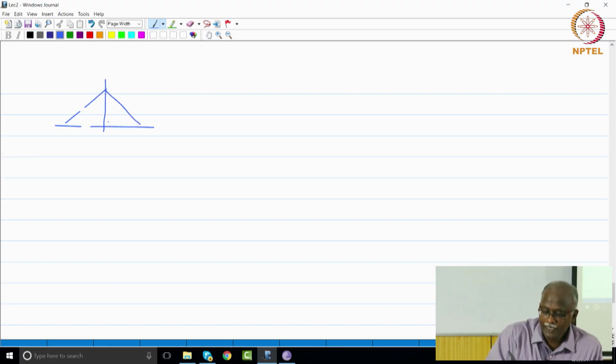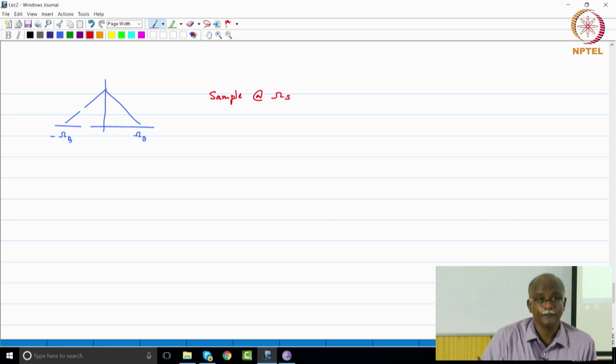Now let me ask this question. Supposing I have a signal band limited from omega b to minus omega b. I want to sample at omega s, but omega s is less than 2 times omega b.